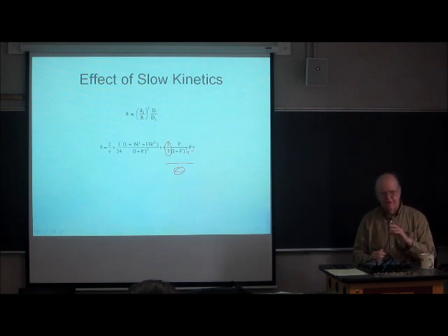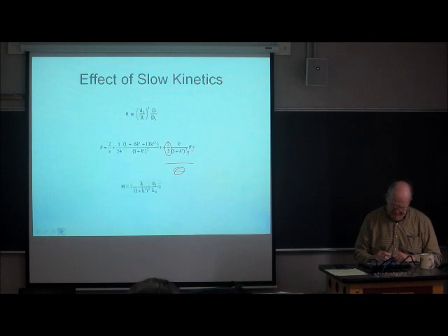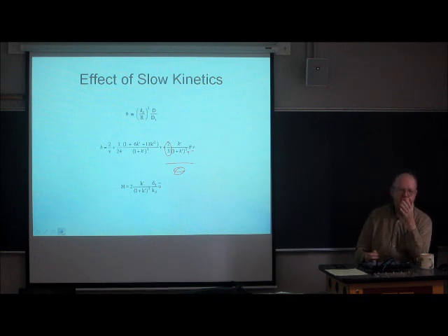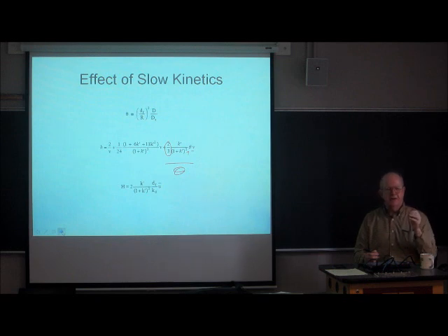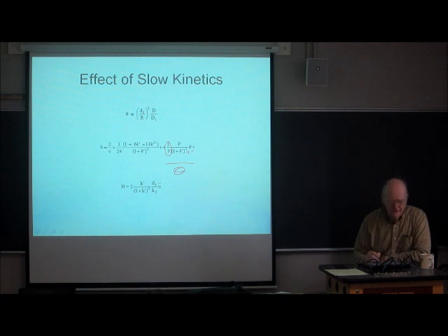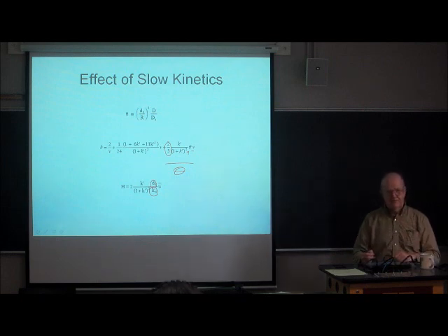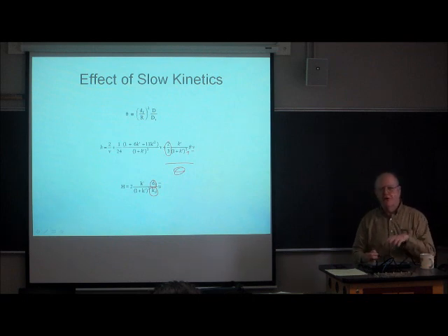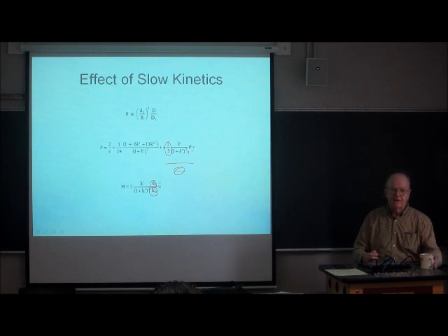Now we can start to look at this in terms of nice simple plots. Oh, I forgot one more thing. When you go to exceedingly thin films, like 1/10 or 2/10 of a micron, you start to pick up some sensitivity to slow interfacial kinetic effects. The slow interfacial kinetic effect depends upon the film thickness and the rate constant for crossing that interfacial barrier. That's a chemical rate constant now. You can't really predict what it is. It depends on exactly what the solute is, what the stationary phase is, and the temperature. So I can't do any more with it than this. I can't predict it, but you're only going to see this contribute to the HETP when you've got very thin films.